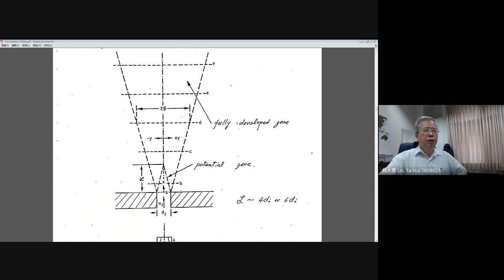The potential cone is usually used to analyze the position of the premixed flame, because the premixed flame is determined by the balance of the supply velocity and the flame speed. Usually the flame length is small. I hope you remember this from the previous section on premixed burning.